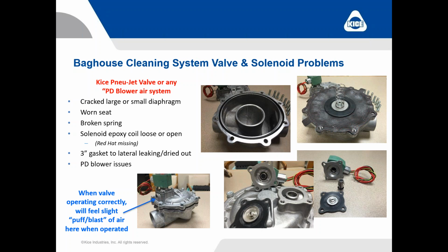Sometimes when you're not able to build pressure in your air tank, if you go through and just put your thumb over that, you may be able to feel air leaking out, or once you put your thumb over a valve that's leaking, you may immediately start to see that the air tank begins to build pressure again. So not the way to find which one's bad, and not always the right way or easiest way, but again, just another idea to think about and something to help you pinpoint where your problem may be.